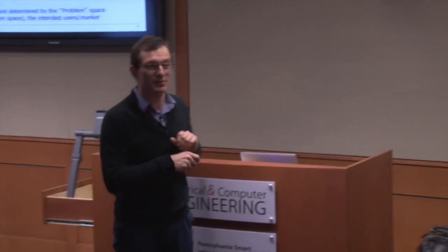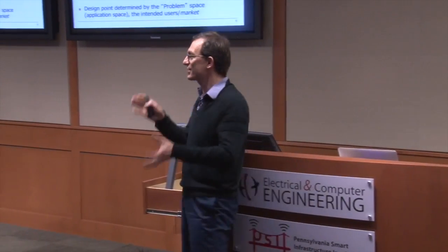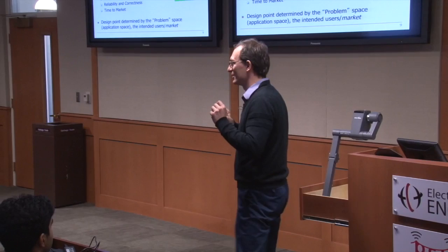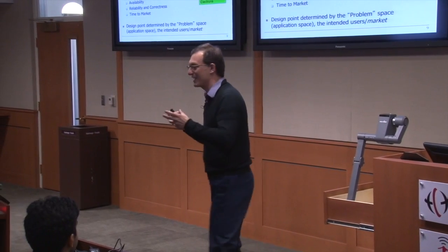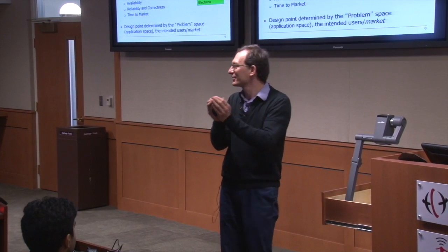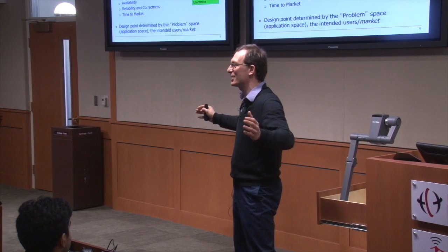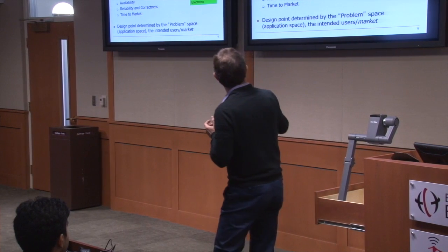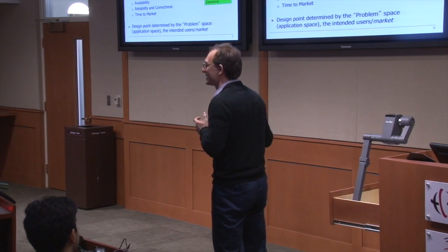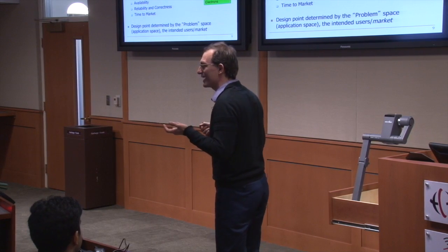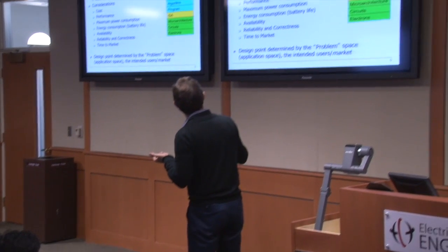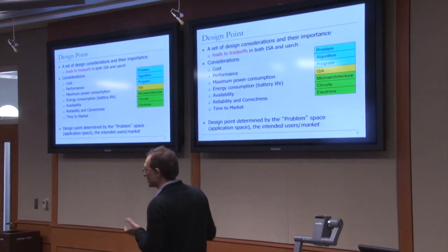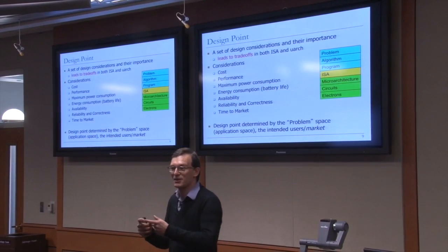But cost is one of the big drivers, right? Remember we talked about the adder implementation before. Do you do a bit serial adder with just one full adder, or do you implement a carry lookahead adder? Well, that has implications on maybe all of these, right? Cost certainly, but bit serial adder is much less costly, but it's lower performance, and by itself it doesn't consume a lot of power, right?